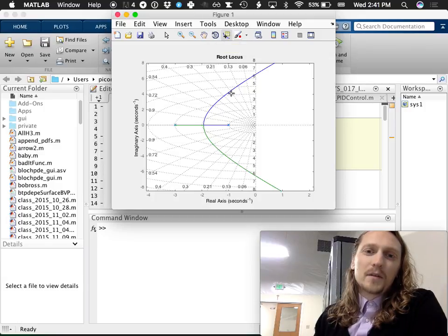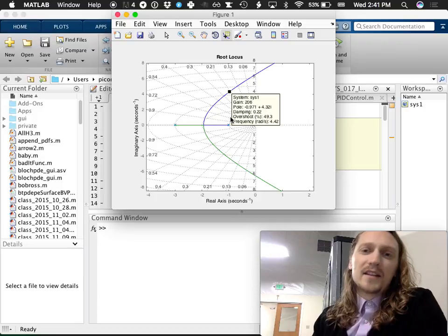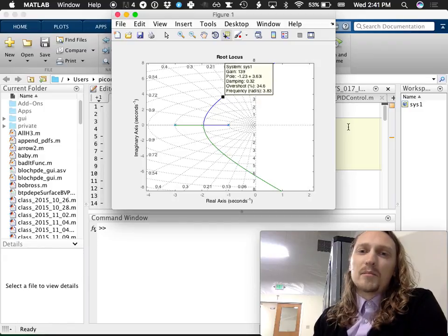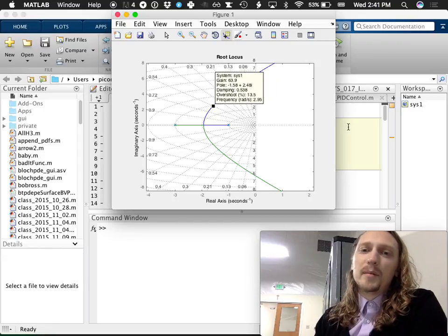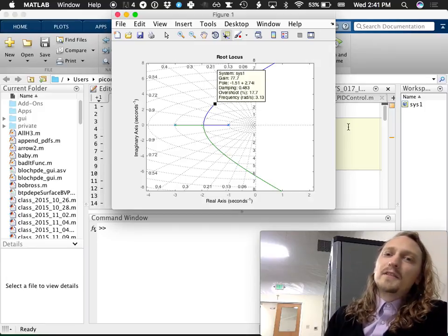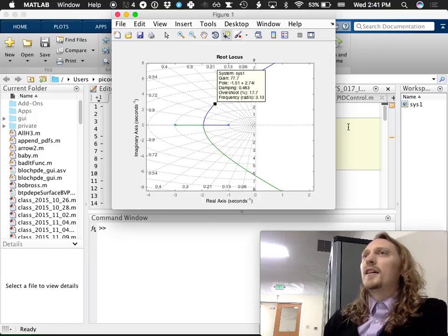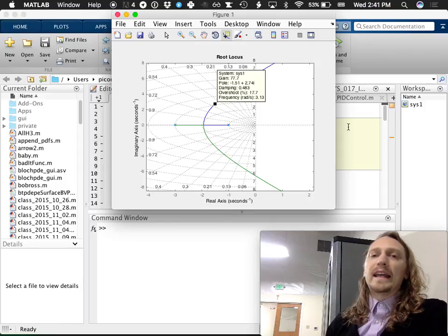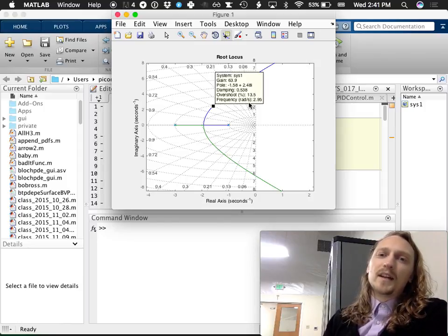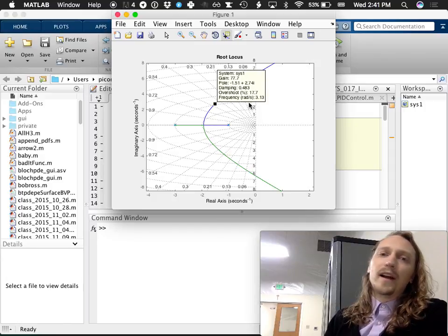have 15% overshoot. We could compute what the zeta line is we need to be at, but it's kind of convenient that MATLAB has percent overshoot pop up here for us. So this is it. I can't get to 15. I can get to 13.5 and I can get to 17.7 with the native resolution that they give me on the root locus. But I can't get 15 exactly, can't get any closer than that. So my gain's between 64 and 77 probably.